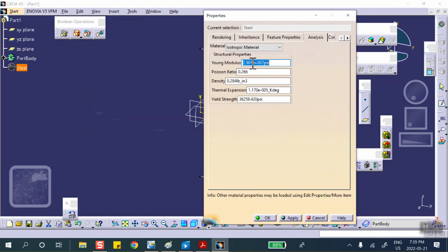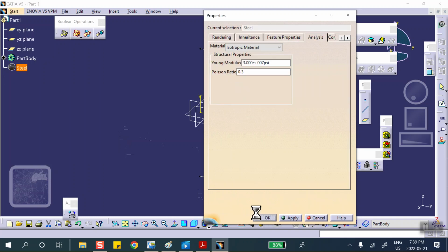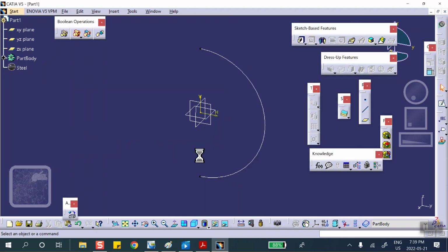So if you want it exactly the way I've described it, you can change the Young's modulus and make the Poisson ratio 0.3. I did not expect you to do that, and on the test, you should know how to change it, but I'll try to say use default properties unless you're specifically asked to change it. Okay, good. So I changed that.